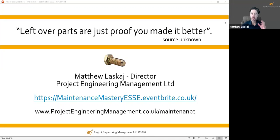Yep. As I said, just make sure that the two things you think about is the task that you're doing, is it appropriate for the consequence that you're managing? If you're happy for it to fail because you can manage the consequences, let it fail. If the consequences are too great, then you have to do some maintenance and think about, is planned maintenance going to give you the most accurate task to prevent that failure or predict that failure?